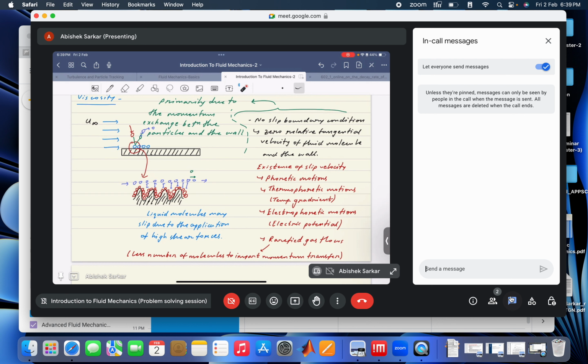It's not perceivable because there are layers and layers of gas molecules above these molecules that are in contact with the wall. These molecules exchange momentum between the wall and other gas molecules, which are tightly packed, although not as tightly as in liquids, but still tightly enough for a proper transfer of information from the wall to the other molecules via momentum transfer that the wall is at rest.